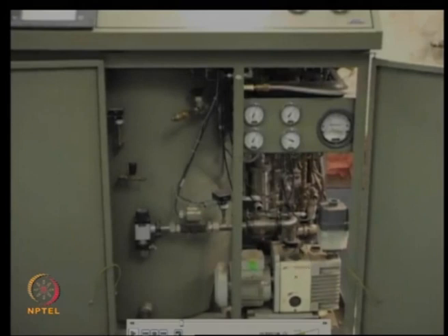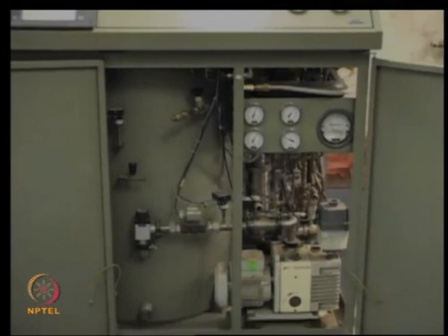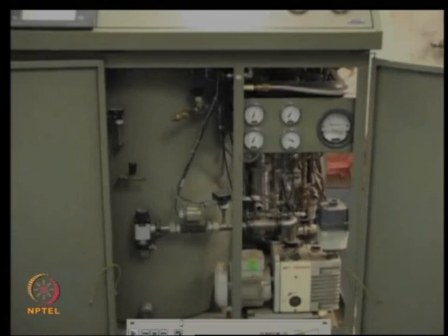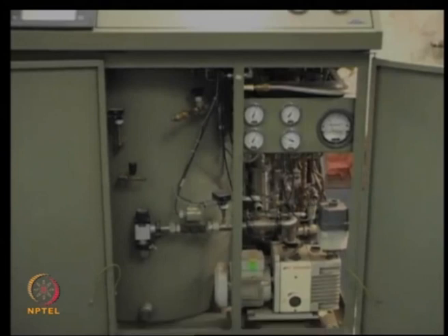There is a rotary pump, and whenever you want to start the plant, first you will start the rotary vacuum pump, so that you get a good vacuum out there, and then you will start the compressor later. So, this is normally called the cold box, which houses the heat exchangers and the expansion engines, and there are various pressures which are recorded, the vacuum which is recorded, all those dials are shown over there. Many times nowadays these are all digital dials also.